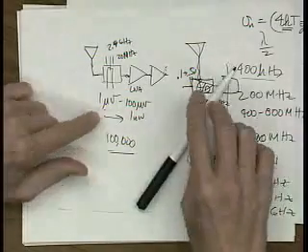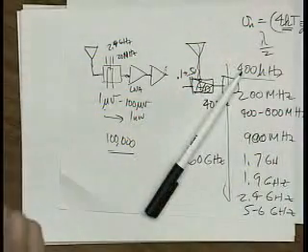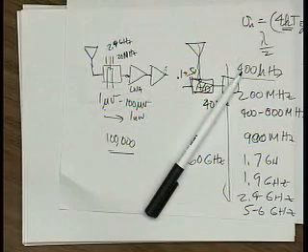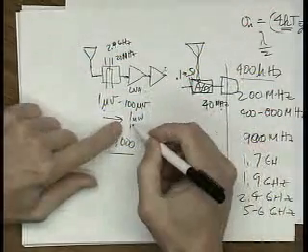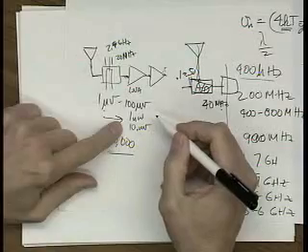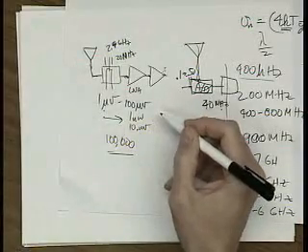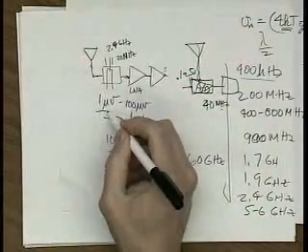Because think about it, if you're sitting underneath the cell phone tower, that tower is putting out 100 watts, and your little cell phone sitting right below it is getting just creamed with power. When you're right next to the tower, you might be getting 10 millivolts into your cell phone. At the edge of the cell, it might be 1 microvolt.